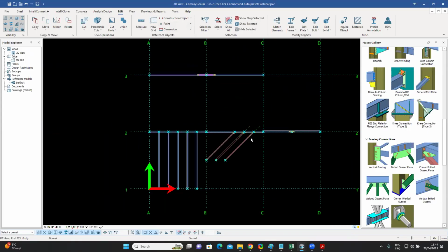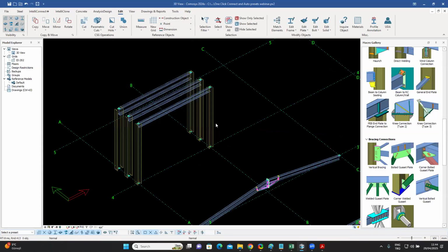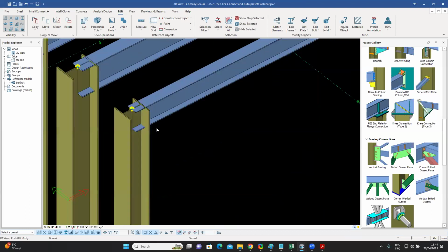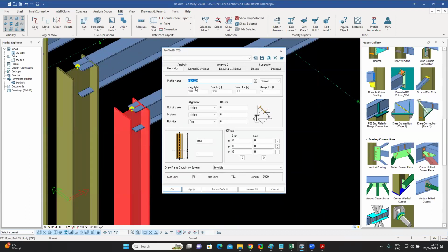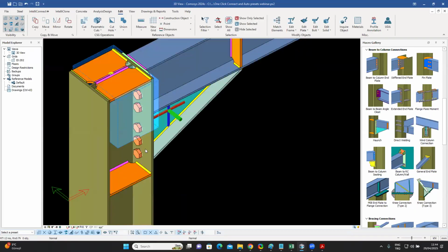Now, another example I can do is of flange bolting. So let's come over here. This is an I-beam, HEA 300. Let's say I make a haunch connection over here. Now, one thing which always takes time is whenever you place bolts on the flange of an I-section or on the flange of a channel, the exact location of the bolt is specified by the standards.